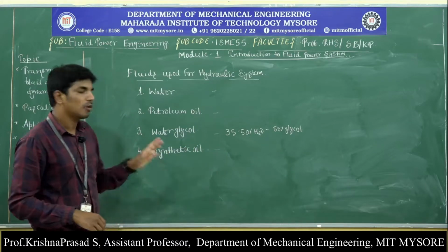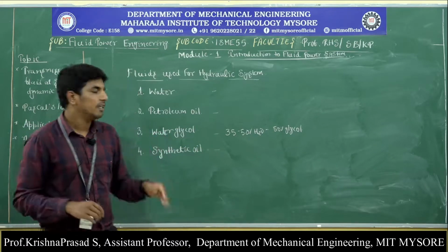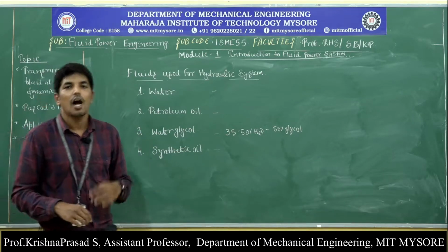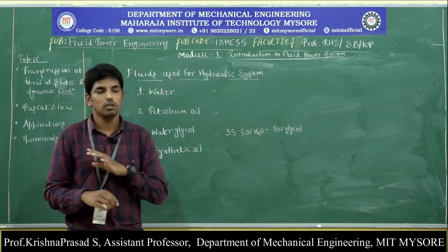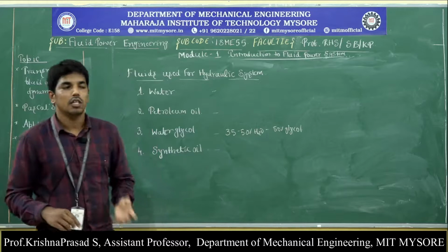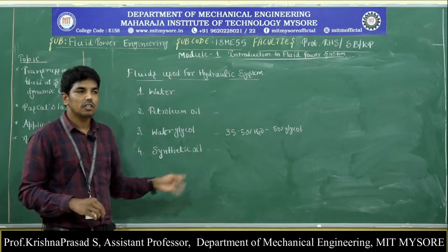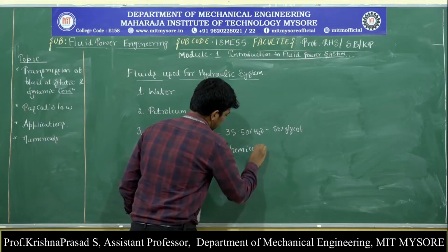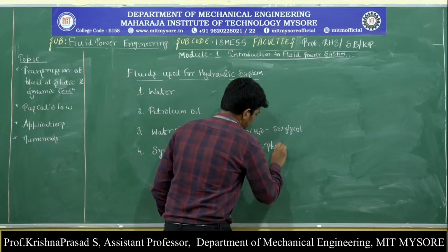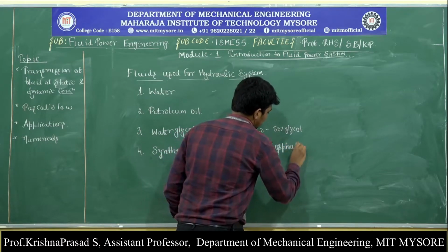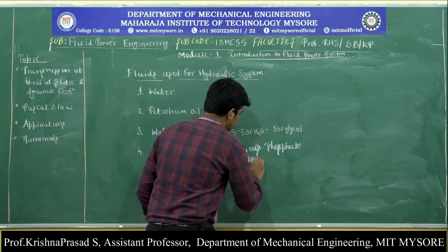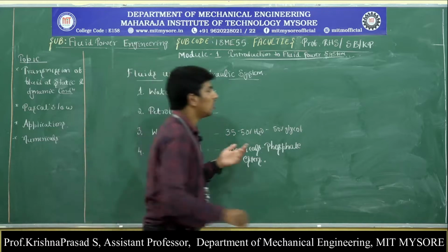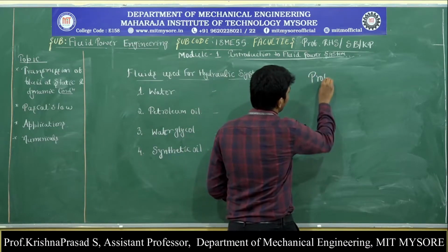And the next one: what is meant by synthetic oil? Synthetic oil is also a non-flammable fluid, and the main advantage of synthetic oil is that at higher temperature it will not burn and does not lose its viscosity. That's why synthetic oils are used. These synthetic oils are made from chemicals known as phosphate esters.